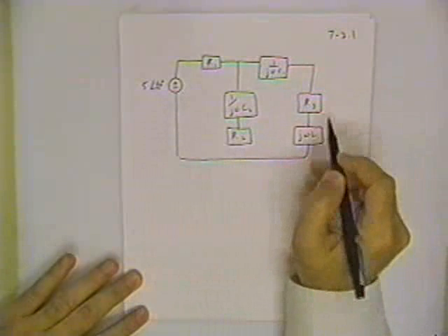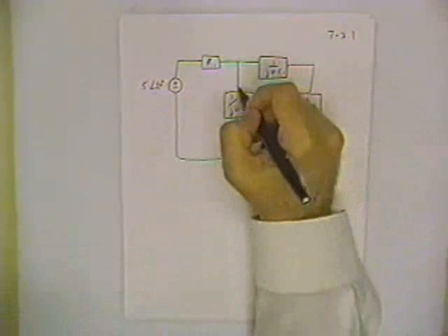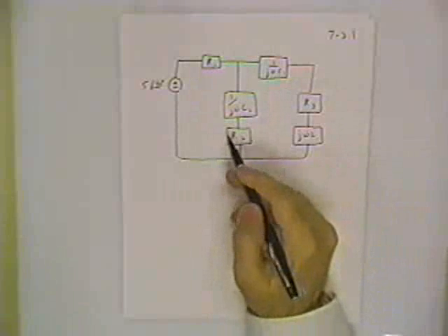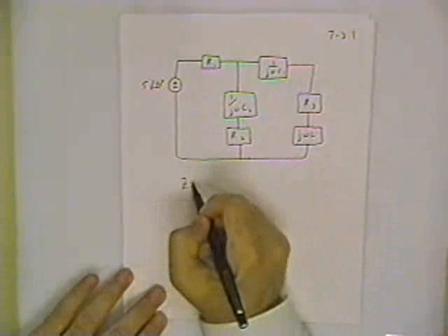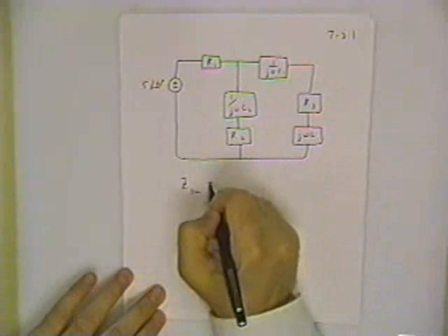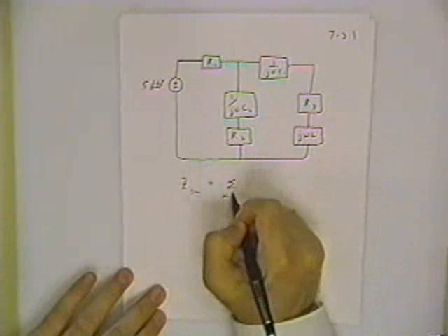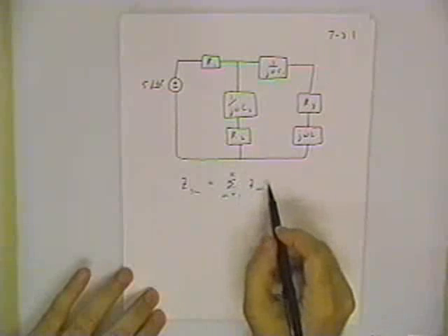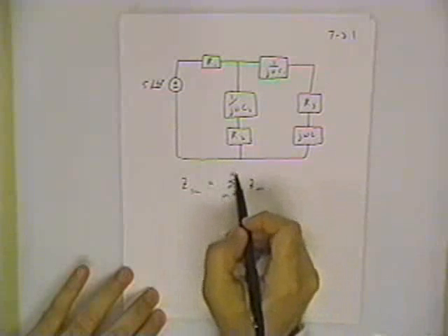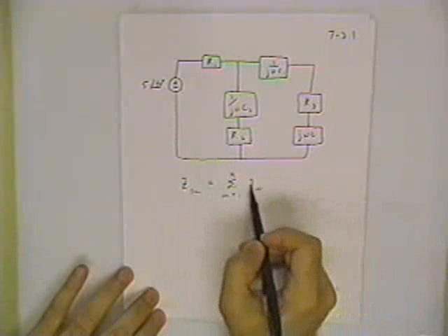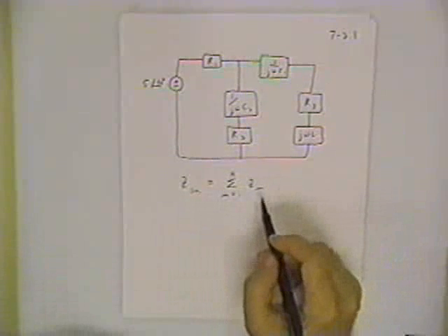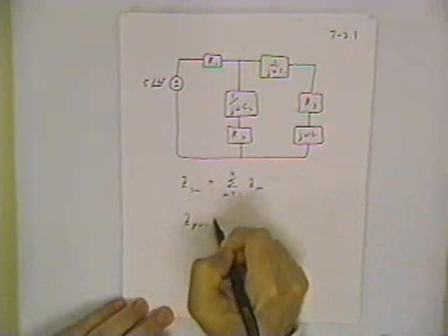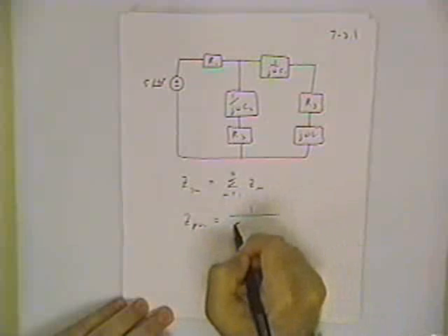Now the question is, what do you do with this? What you would do is simplify this circuit using series and parallel combinations. And that's a key concept: in series connected impedances you have the same sum rule we had for series connected resistors. If you have capital N impedances all in series, you just add them up algebraically, remembering to group the real and imaginary parts. You come up with a complex number equivalent here. For parallel connected impedances, you take the inverse of the sum of the inverses.